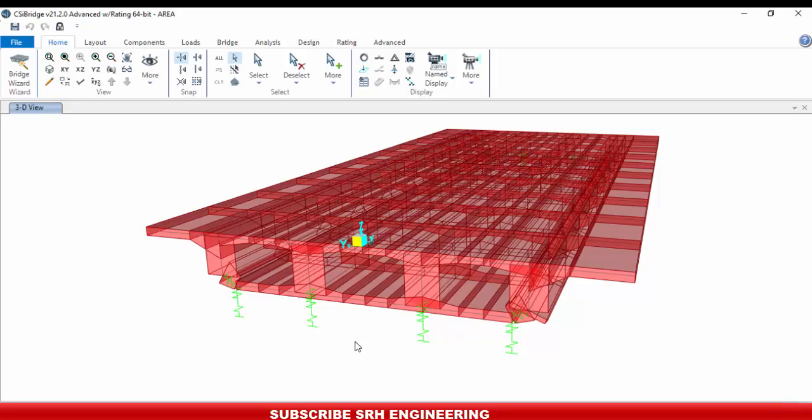But sometimes when you have a curved bridge or skew bridge, you are getting more bearing reactions for the self-weight load case. If there is an uplift due to the curve or skew in the bridge, and you are depending on the self weight of the bridge, then it means that you are taking a risk. So my suggestion is to get the actual bending, actual results, and the actual bearing reactions.